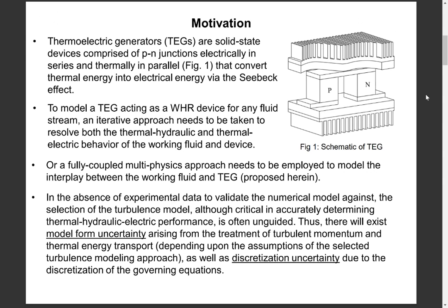Thermoelectric generators are solid-state devices comprised of hundreds of p-n junctions positioned electrically in series and thermally in parallel. These devices convert a temperature gradient into an electric potential via the Seebeck effect. A single junction within a TEG is shown in Figure 1.